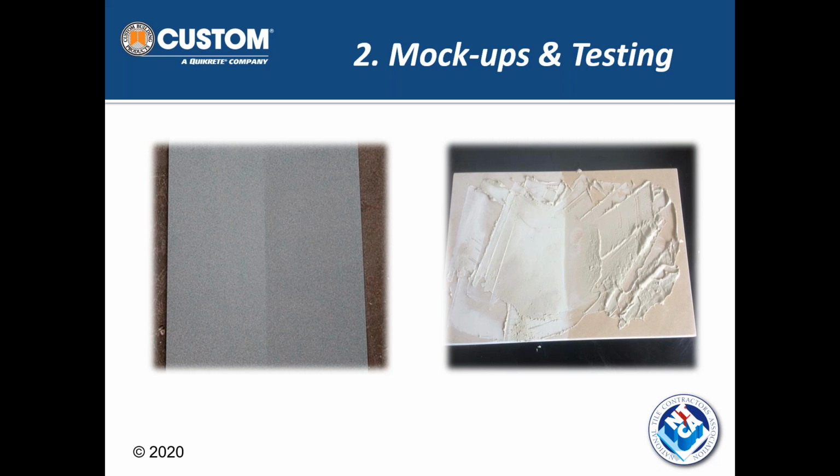Picture on the right is, again, some limestone. What I did here was pre-seal the right half with a color enhancing seal. Then I grouted it. I just put some cement grout on top of it to simulate what happens. Notice on the grout on the right side where I put the color enhancing seal, notice the color difference. It's still dark and it still looks wet, which is what you want it to be.